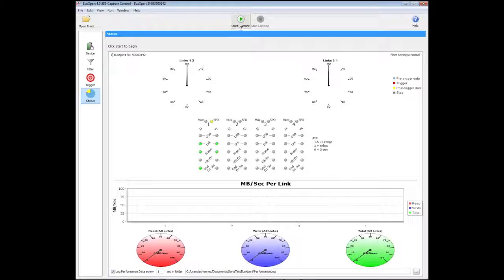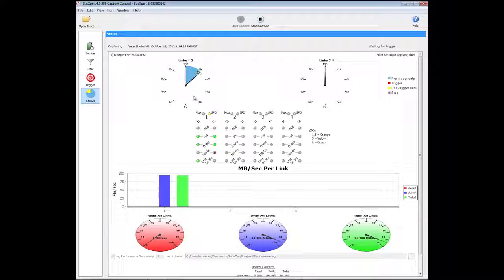Now when I start the capture, I see the capture buffer being filled, my 18 gigabyte capture buffer. I can see it's about 50% filled now, and it's just first in, first out. When it wraps around, it's continuously capturing the latest traffic. I'm also seeing the status LEDs. In addition to the link LEDs, now I have frame traffic going across the link. I can also see an LED indicating commands are moving across this link.